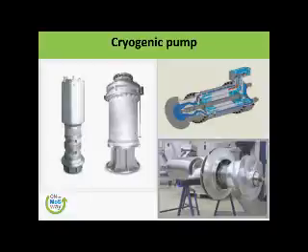One thing which you need to remember is that these pumps are not designed to run on empty tanks. So it means they need to be submerged in a certain level of liquid so that they can operate. So once the liquid level is somewhere here, then of course they can operate.